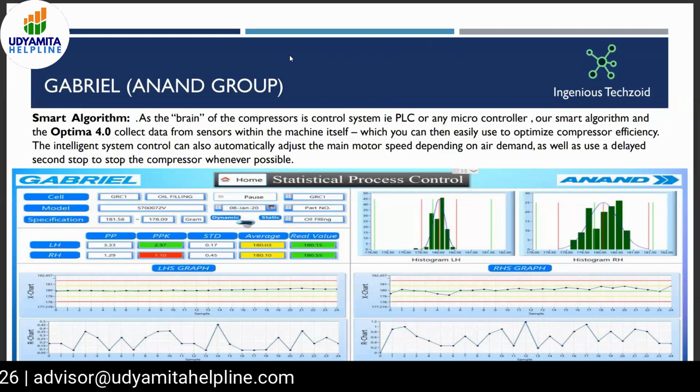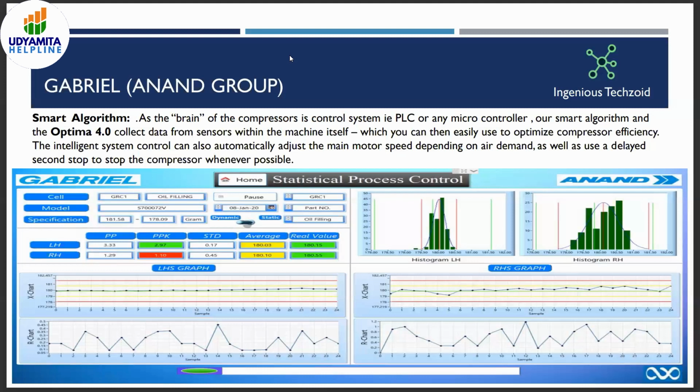As I showed you, we have made the mean chart and range chart. Sometimes, if I'm manufacturing a soap, I need to maintain my temperature somewhere around 45 to 47 degrees. Above 47, the quality of my product degrades, and below 45, the quality also degrades.